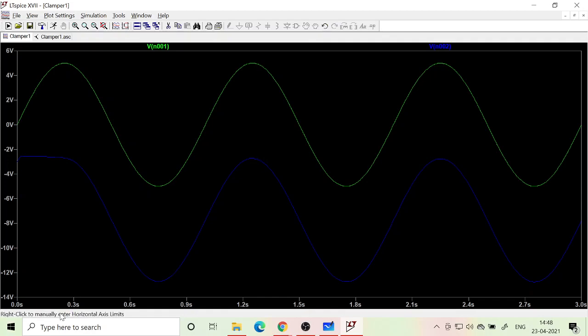Now you can see there is an xy coordinate here. Here if you look at x is equal to 0, y equal to minus 14. So depending upon where you put the cursor, you can find it. We need the y value difference. The y value here is 5, that we know already. And what we need to know is what is the y value here. It is minus 2.76. So 5 minus minus, that means 5 plus, so that is 7.7.